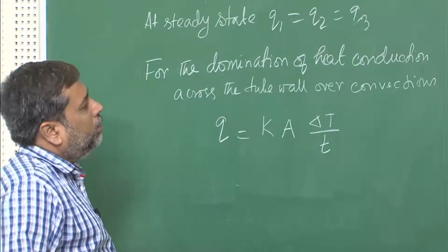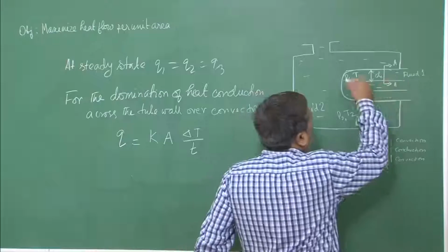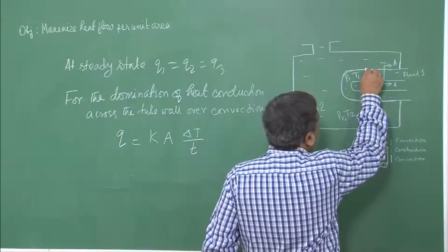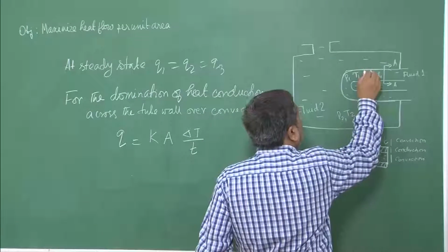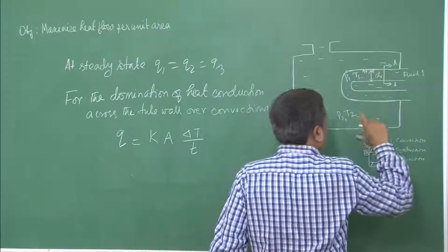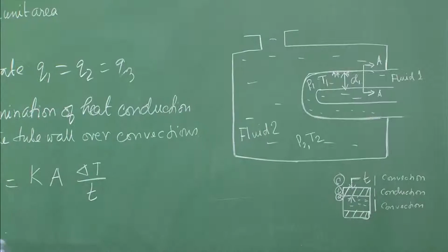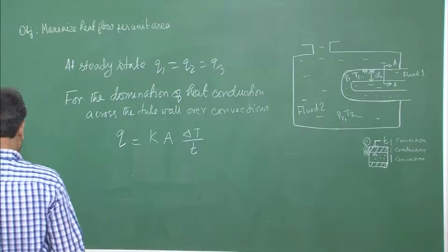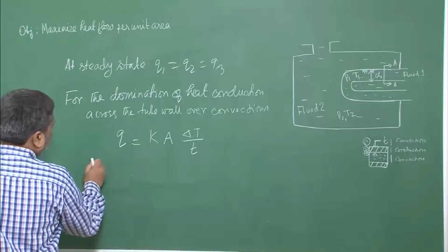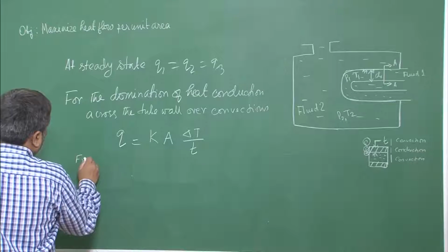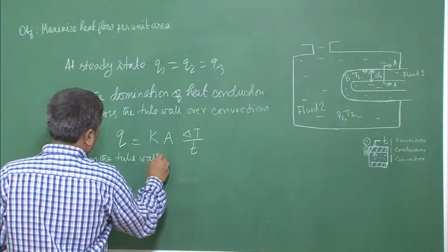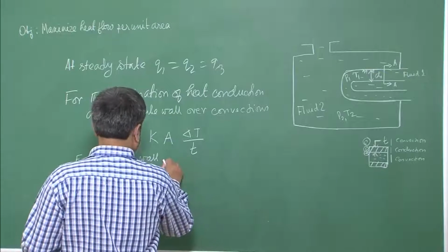Now, during this transfer of the fluid at pressure P1, this wall is also subjected to some stress, something like a hoop stress that is happening in the wall. So, it is trying to expand the wall. From the mechanical point of view, it has to withstand that pressure also. So, the stress that will come in the tube wall, from the tube wall stress point of view,